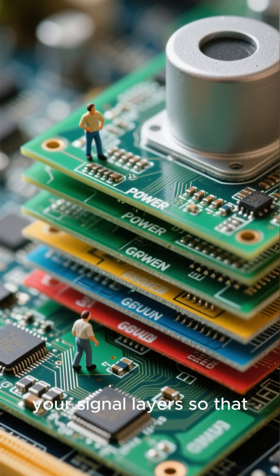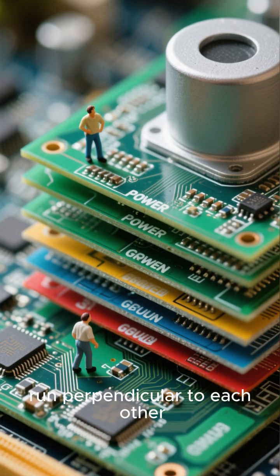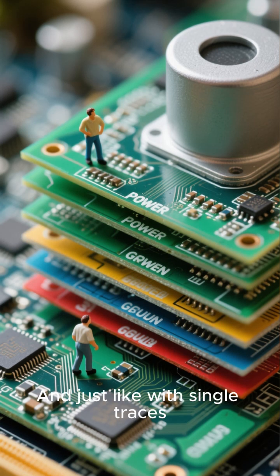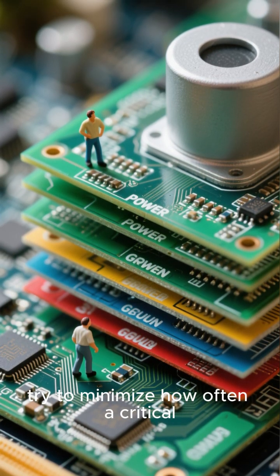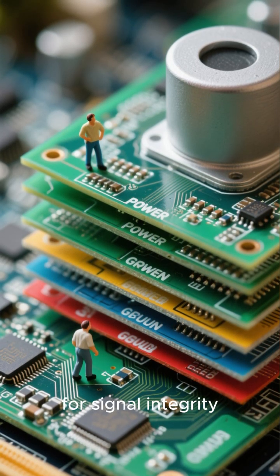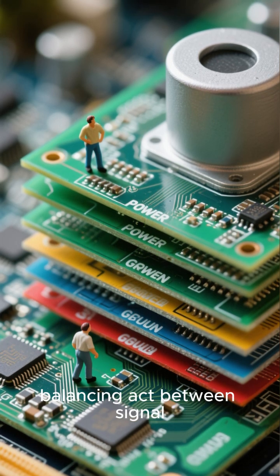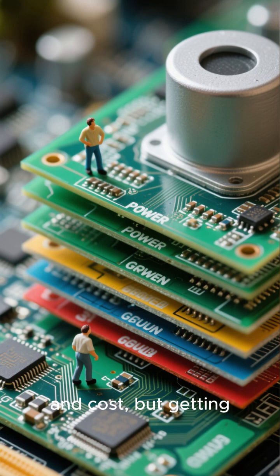Try to arrange your signal layers so that if they are adjacent, the traces run perpendicular to each other. This minimizes crosstalk. And just like with single traces, try to minimize how often a critical signal has to switch layers. Every layer change is a potential point of failure for signal integrity. Proper layer stack-up planning is a balancing act between signal integrity, thermal performance, and cost, but getting it right is a game changer.